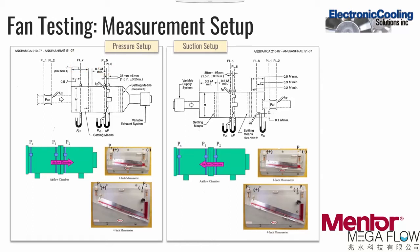Bernoulli's equation coupled with the continuity equation is used to compute the airflow that passes through the nozzle. This is easily calculated using the Excel sheet that is provided along with the airflow chambers. During fan testing, either of the configurations can be used. Let's consider the scenario where a fan is attached to the chamber and is blowing inside.